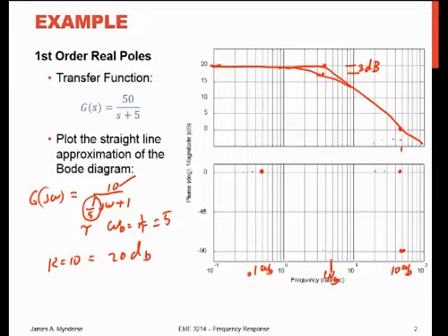For a single pole, we start out with 0 degrees of phase lag. We cross through our break frequency at -45 degrees, and we hit -90 degrees at our 10 times point, and I'll try to draw as straight as I can. So that goes like that, and then we flatten out at -90 degrees of phase beyond that point.